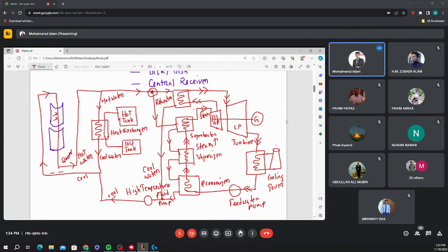That is your superheater. So suppose I am just considering that from this valve, the temperature should be high here. The water temperature should be high here, so it can superheat the vapor. After that, the temperature will be low and it comes to the vaporizer. So to vaporize the water, you need only 100 degrees centigrade, right? That makes sense. So maybe the temperature is medium here. And after that, the economizer means to preheat. We can say this is the preheater. So maybe you need 50 degrees centigrade here. So we can say the temperature is low here.